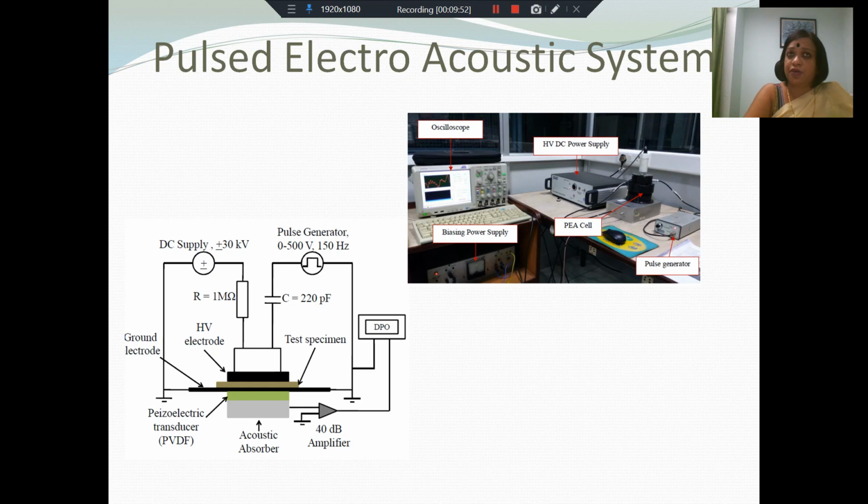There are very few direct techniques; there are also indirect methods of space charge measurement. In fact, we have talked about polarization and depolarization current measurements in the earlier lecture. That can also be used to measure space charge. We can use electroluminescent techniques as well. So there are very many techniques available. But this pulse electroacoustic system I am discussing separately, specifically because it gives us additional information.